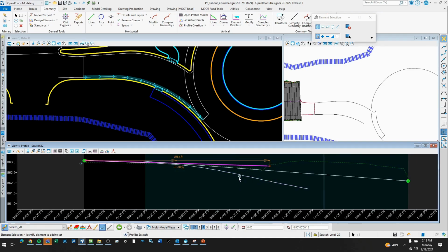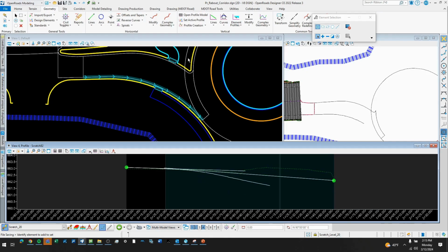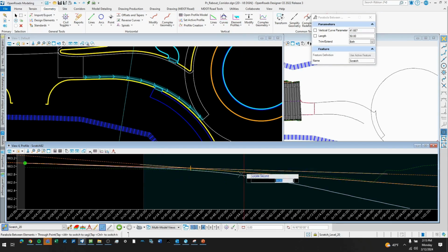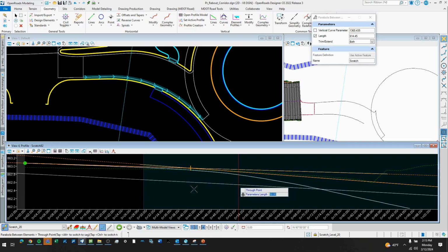And obviously these are both negatives, so really you're only looking at that 0.45 times the crest, which was 19. It's very, very small for sight distance. I'm just going to put the curve at another 50, just to have that extra space.